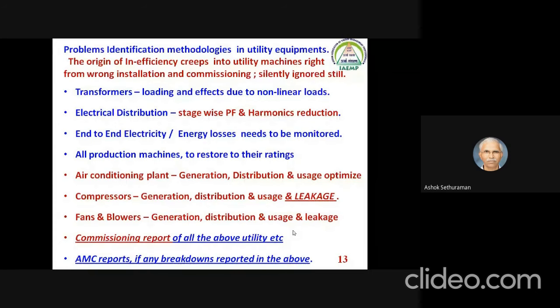In many of the recent happenings in IoT, for the usage, they have done a lot of automation in the USC to optimize the usage. But generation also is important. We are talking about 2 kilowatts per ton. Now it has come to less than 0.5 kilowatt per ton, thanks to all the magnetic chillers that are coming in the packages, but chillers are coming with a huge cost. On the existing HVAC plant or the chiller plant, how much can you reduce?